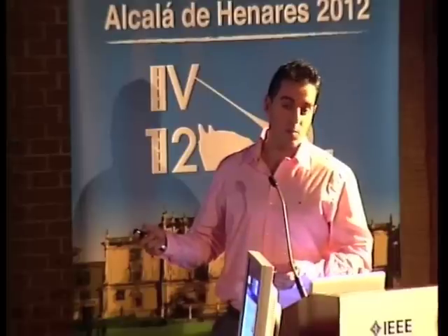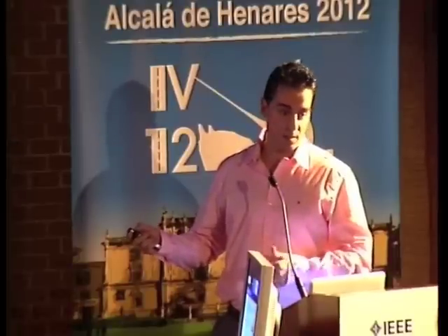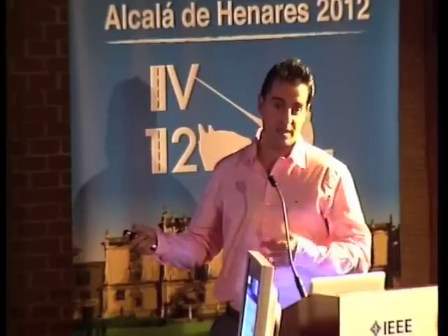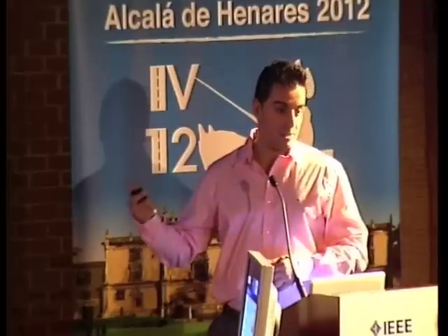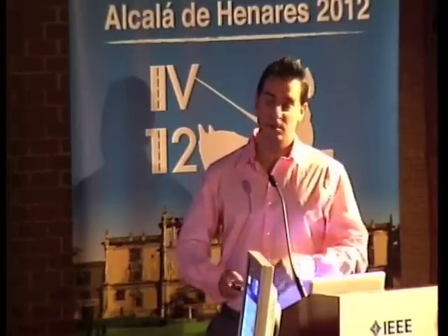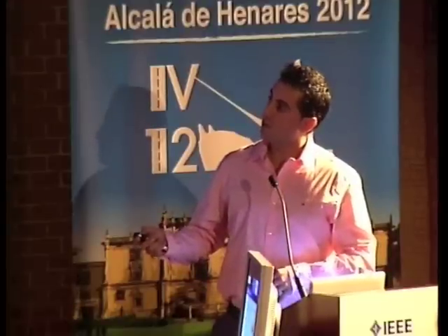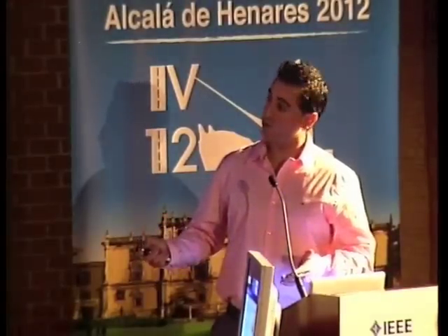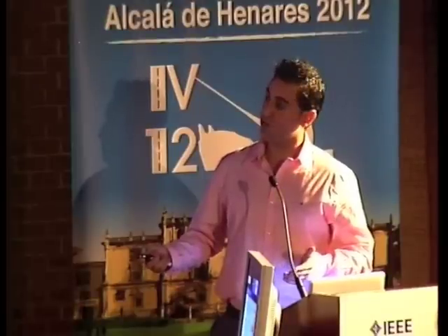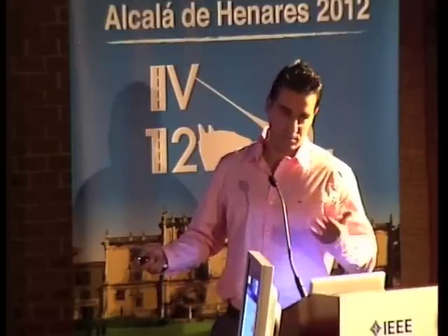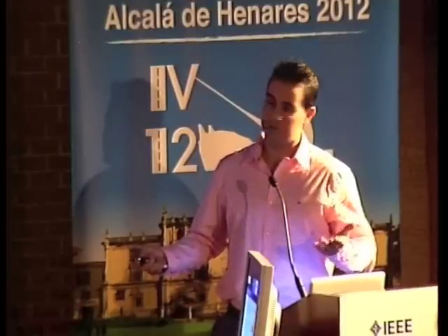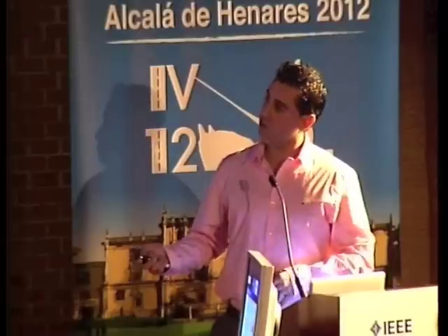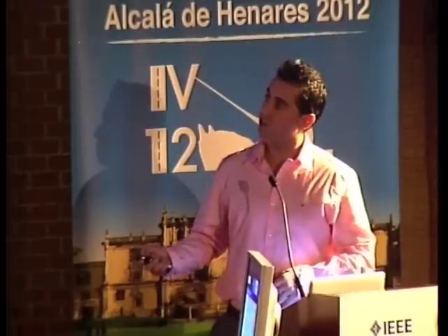With a room convolutive model, we can estimate the microphone responses, so we can estimate the mixing matrix and we can invert it in that case. So if we only have 8 microphones, we can estimate 8 sources, and we can find the mixing matrix and estimate the source cross-correlation value.